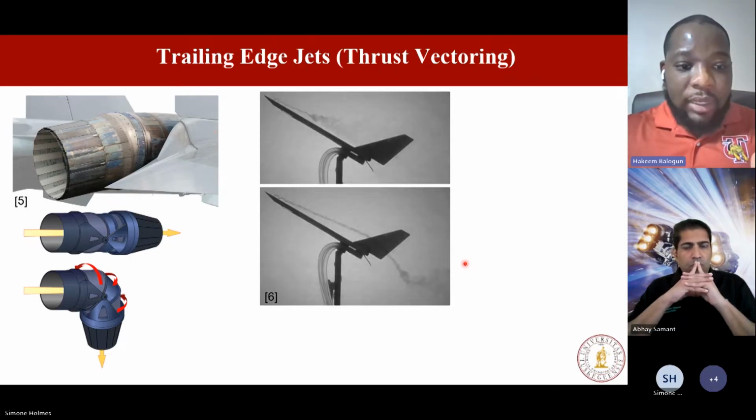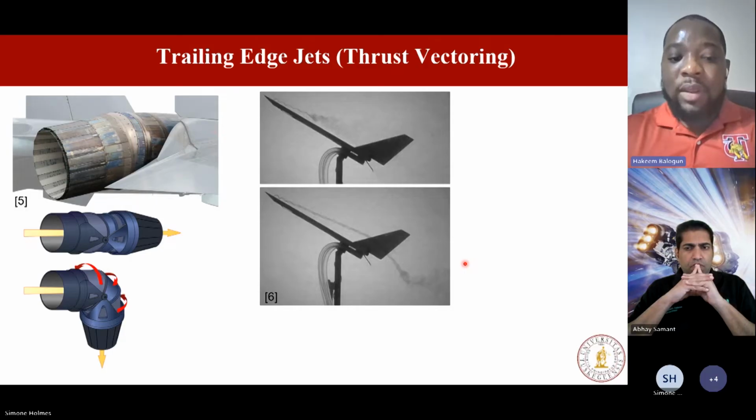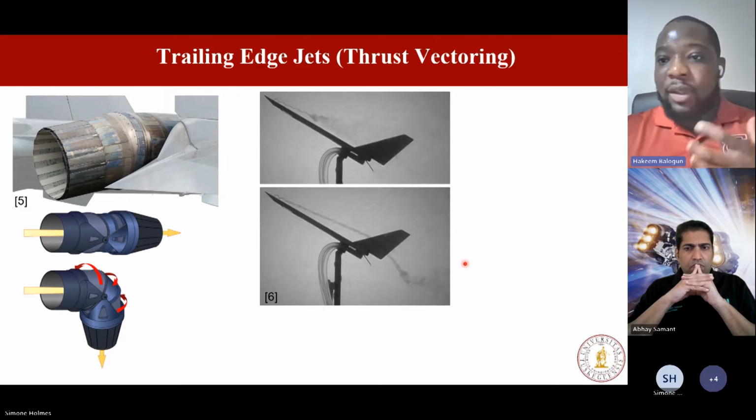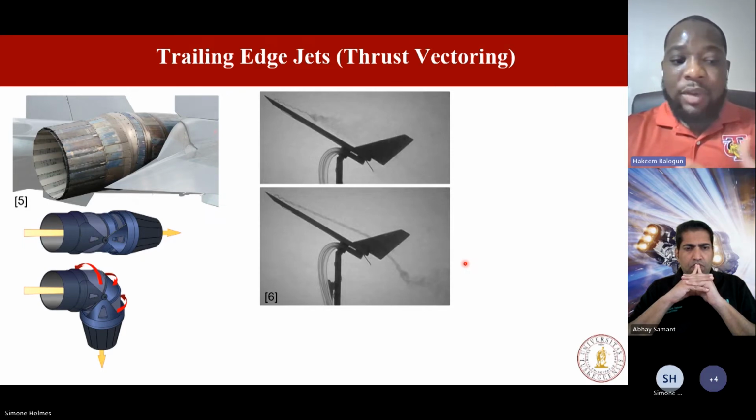This is caused by the jet entrainment effect, where the low pressure region and the vortices produced by the jet exhaust entrain with the vortices produced from the leading edge of the delta wings. This helps to reduce the pressure gradient increase caused by flow stagnation that's characteristic of vortex breakdown.